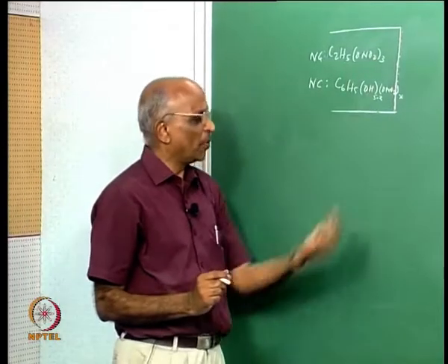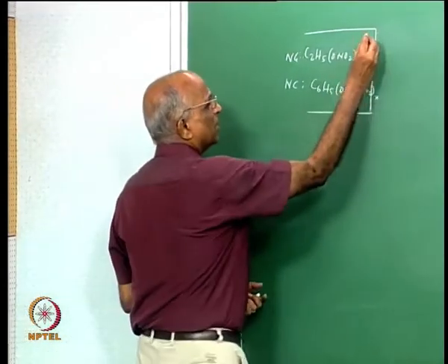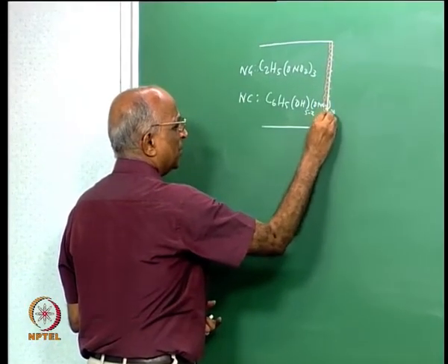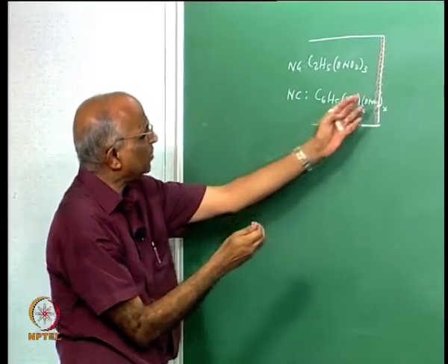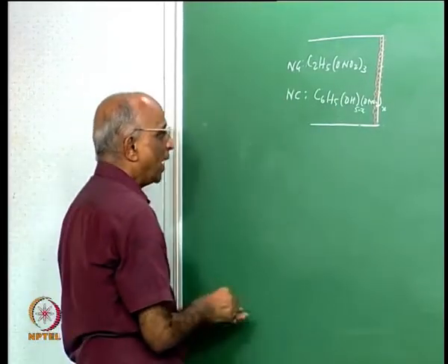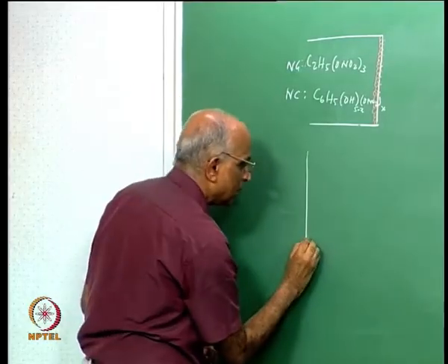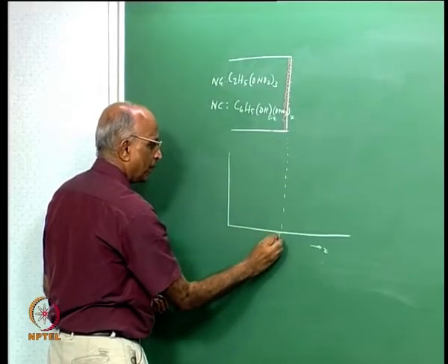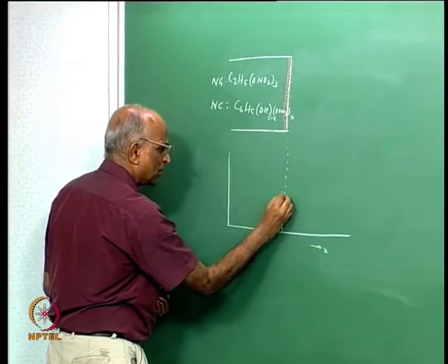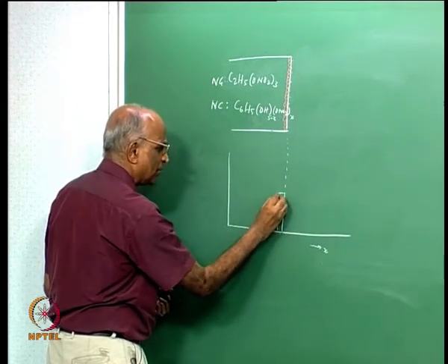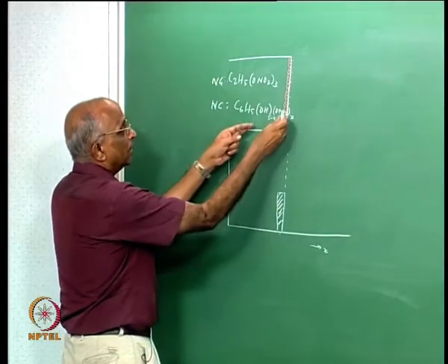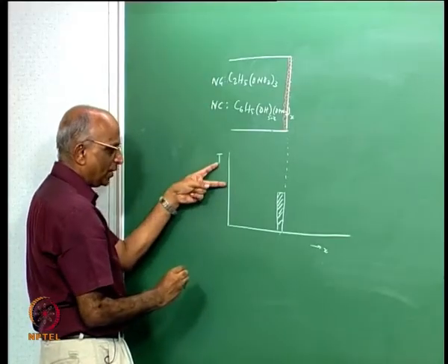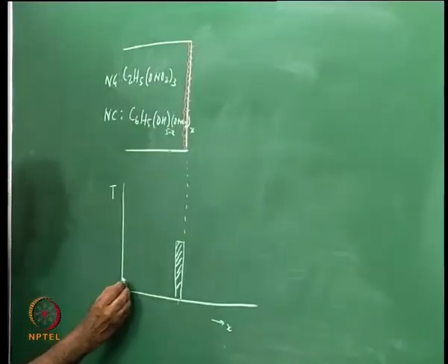Now I ignite the double base propellant, and what happens, maybe a surface very near to the surface gets overheated, because all these propellants are something like an insulator. Heat does not conduct deeply into it, and therefore at the bottom, if I were to consider this as the scale x along the distance, and this is my surface over here, a small thickness of the propellant surface gets heated when I heat the surface, and therefore my curve, if this is my temperature axis on the y axis and this is my distance along, will be something like this.